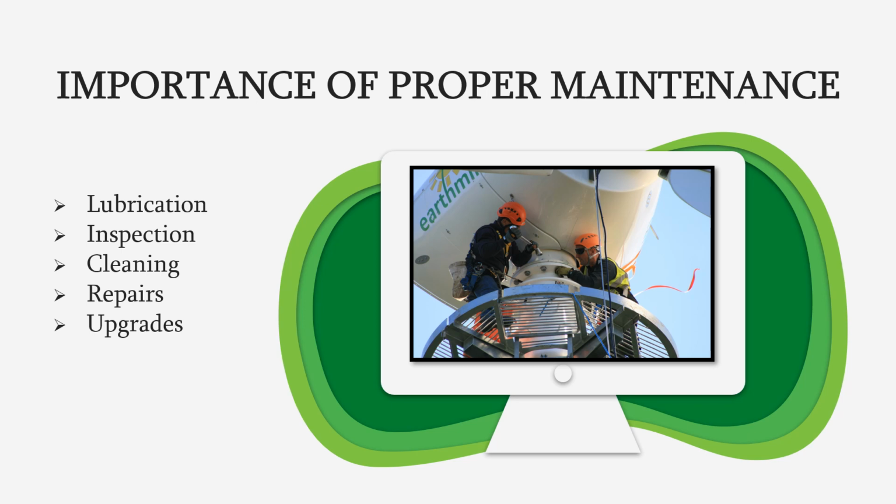Inspection. Regular inspection of the turbine is essential to identify and address any issues that may arise. Inspection includes a thorough examination of the blades, tower, and the other components to detect any damage or wear that may affect the turbine's performance.